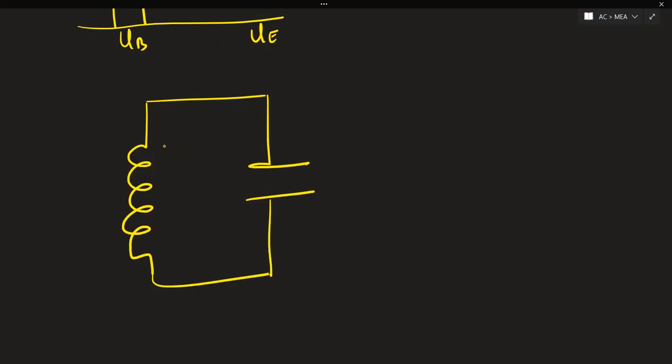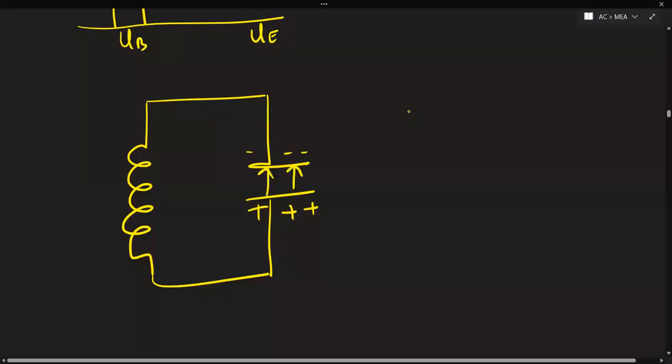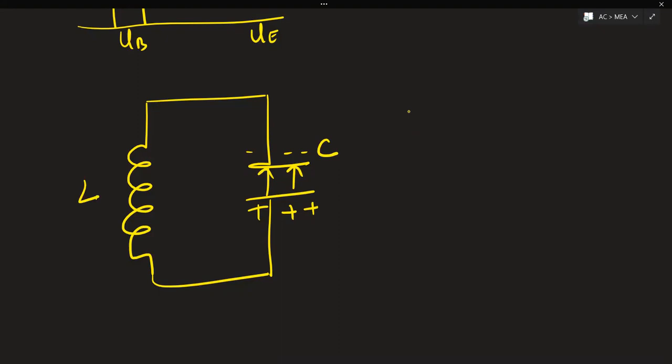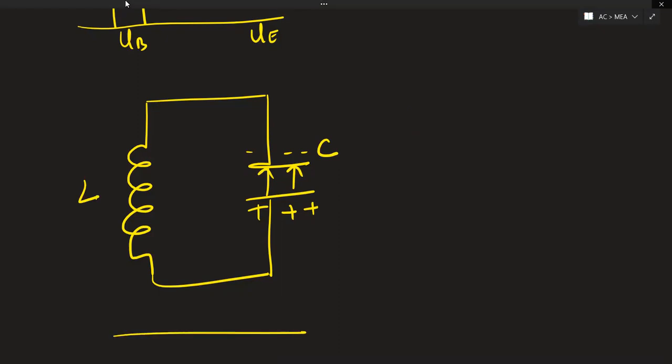As a result, what will happen? According to Lenz's law, or if you just say directly, there will be a decrement in the magnitude of the magnetic field. So it charges the capacitor in the opposite direction. It means this time this will be the positive plate and this will be the negative plate. So now in the opposite direction, charges will begin to charge the capacitor. This is the inductor. Now the reverse phenomenon is occurring.